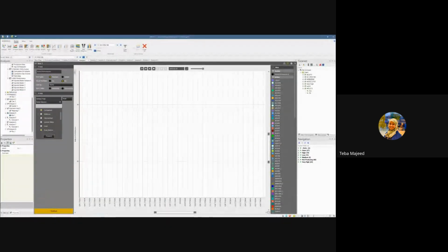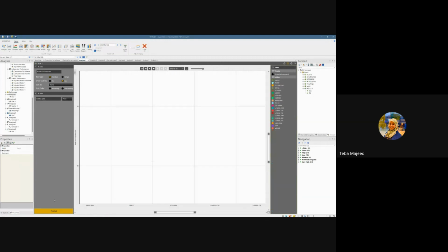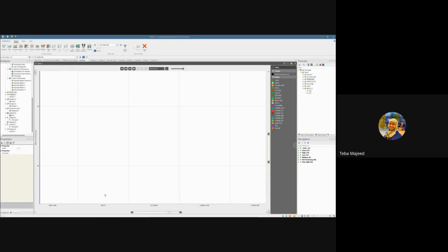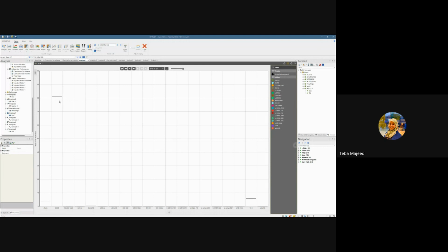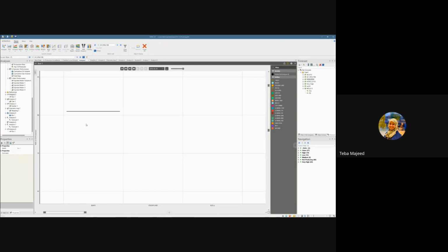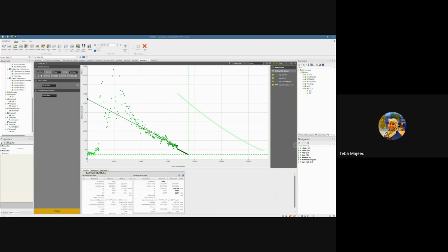So instead of having to recall the data from the database of all the wells, of all fields that you have in the project, you can use the permanent filter to see only the wells that you're concerned with. This way you will reduce the runtime and the amount of data that OFM has to deal with. So this helps you have a very smooth way of using the software. There's a lot of flexibility, and you have the ability to choose how much you want to deal with the database. So that's how you can optimize the software performance when dealing with large data.